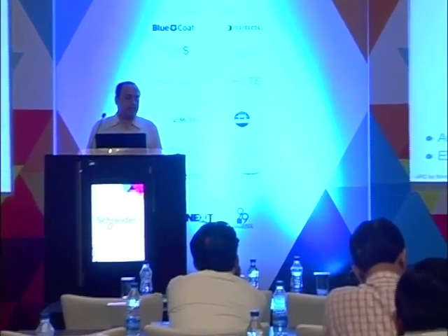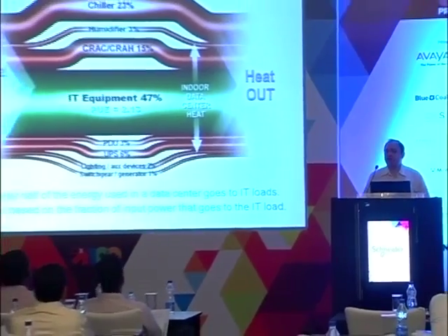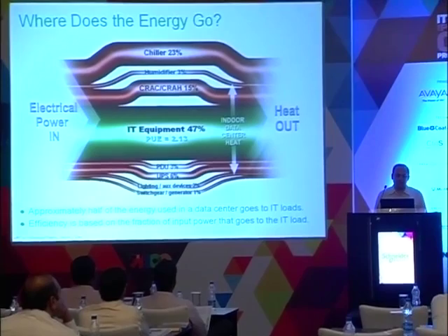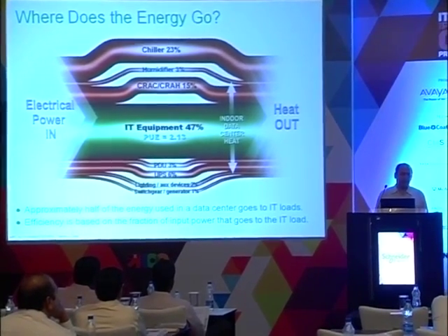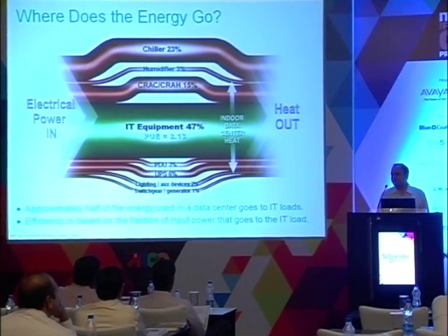So why is that? So the figure answer is on the screen. Cooling equipment consume the biggest chunk of power in a data center infrastructure. So here I am talking about chillers, I am talking about humidifiers and air handling units. The chiller can simply get replaced with what I can call as a compressor if you are using a completely refrigerant based system. But the energy consumption, unfortunately, is in the same pattern, right? So almost double of it is on air conditioning, and air conditioning energy will directly depend upon how much effort you need to take to remove that heat out.